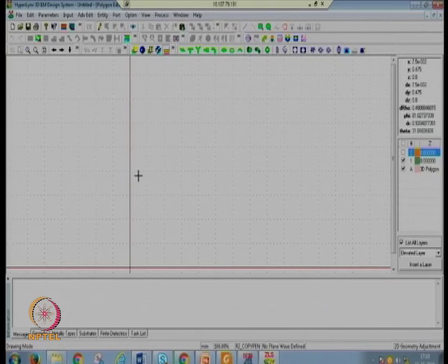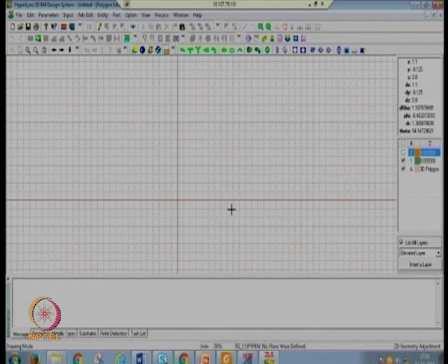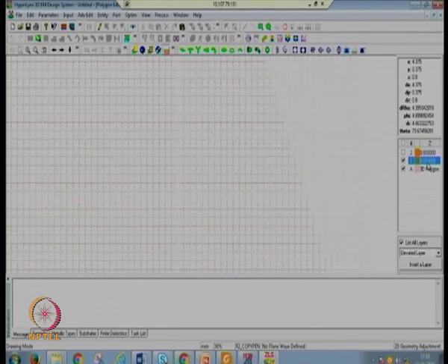Now here you can see this particular section is called the layout editor window, and this one is called the status window. Now if you can see here, if we are moving our cursor, the position of x, y and z, dx, dy, dz, these are changing. So this is showing the status of the cursor, and the dx and dy are the respective location with respect to the last point. Now if you see this section, this is called the layer window. In this section 3 layers are given. This is corresponding to 0.8, this is corresponding to the ground layer.